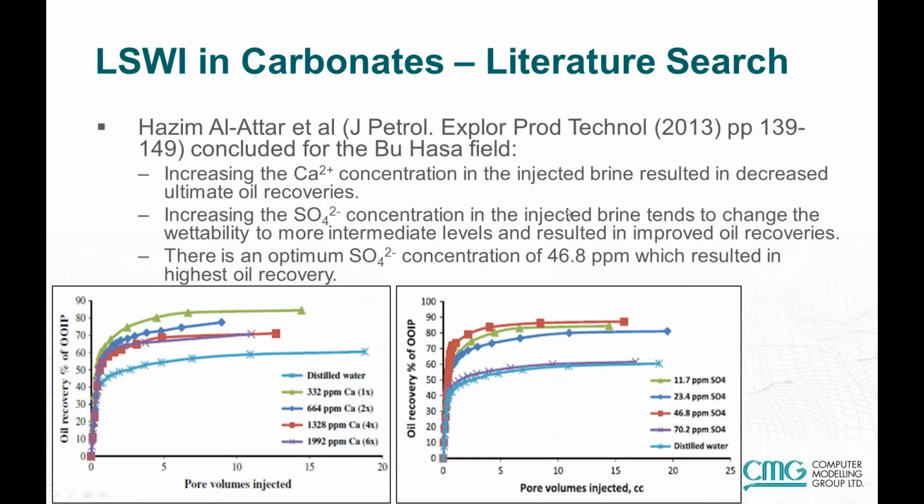Now, there seems to be less understanding of low salinity effects in carbonates. There are quite a few differences of opinion as to the main mechanisms. So for that reason, I'll go through a short literature search here for carbonate. The first paper here is by Hazim Al-Attar in the Buhasa field. It's showing that the increased calcium concentration of the injected brine resulted in decreased oil recoveries.